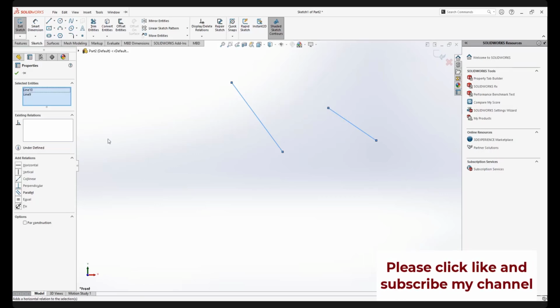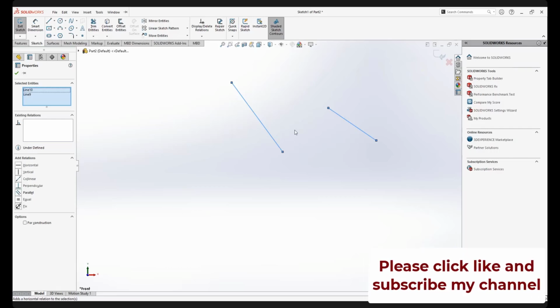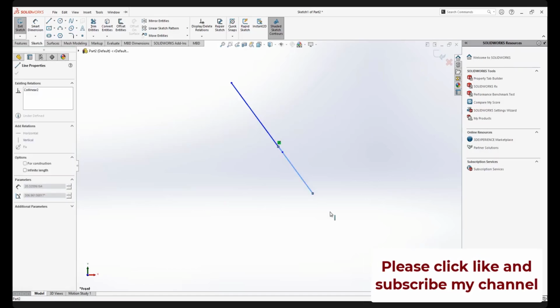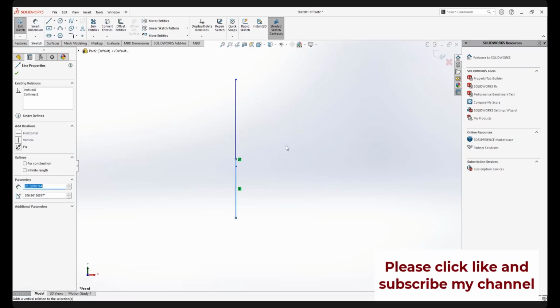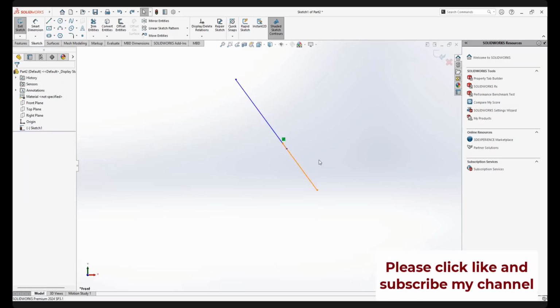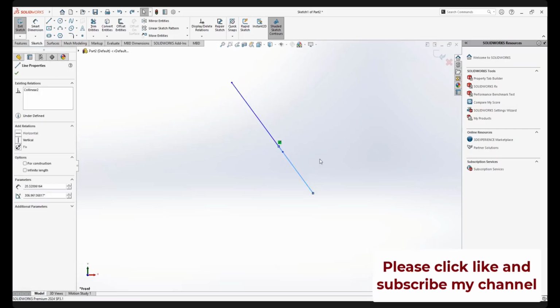Can you see the icon? Also, if you look at the settings on the left, we have horizontal, vertical, collinear, perpendicular, parallel. I want to make this one in line with this. I can choose the setting on the left here, collinear. If I go for collinear, can you see the second line is collinear? Okay, hold on, I accidentally did vertical. Understand, class? Let me undo again.